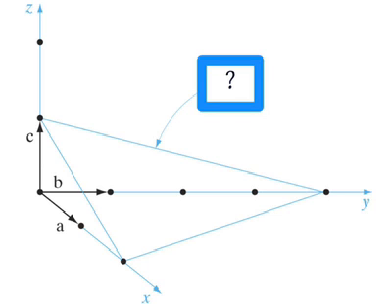Okay, let's do it together now. What are the intersection points in X? 2, so 1 over 2. In Y? 4, so it's 1 over 4, and in Z it's 1. Right? So 1 over 2, 1 over 4, 1. You can leave it at that, that's fine. Or you can multiply it through. Doesn't matter. If you multiply it through, you get 2, 1, and 4.